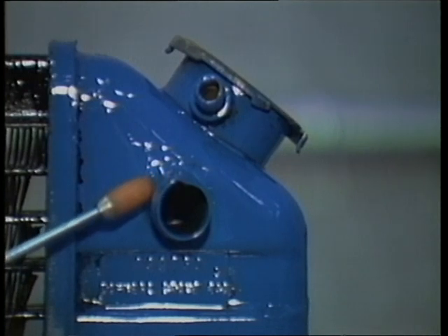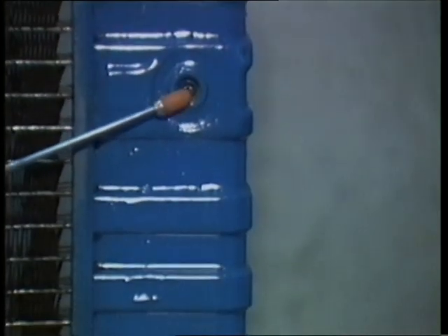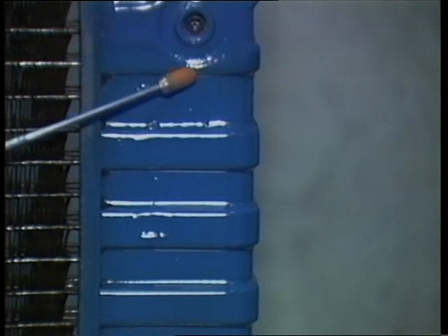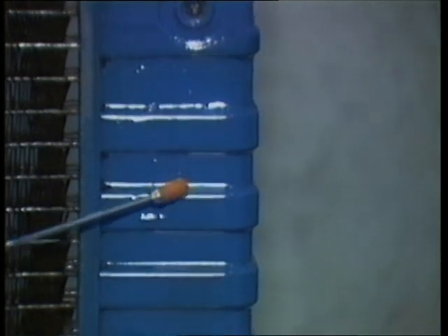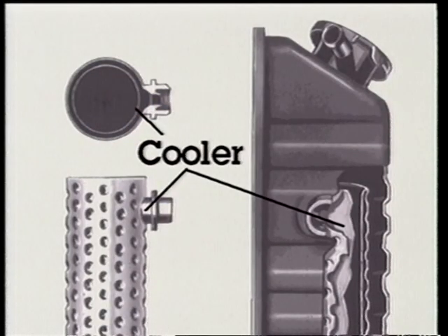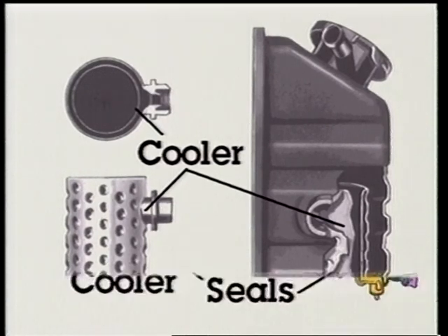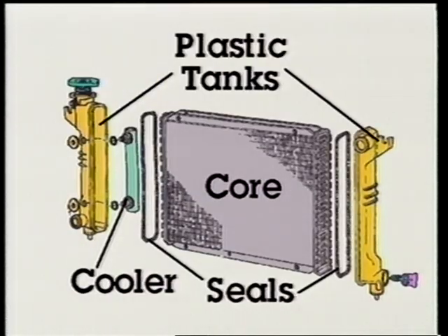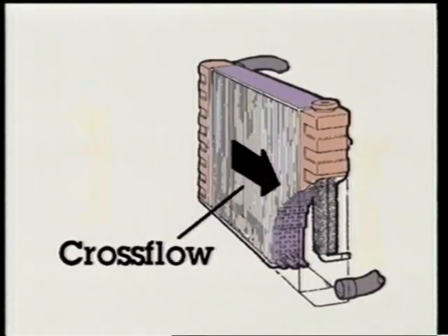Small tube fittings often lead into an oil cooler mounted inside one of the radiator tanks. The oil cooler behind this tank removes heat from the automatic transmission fluid. The transmission's oil pump forces the fluid through the system for heat removal. This radiator uses lightweight plastic tanks.